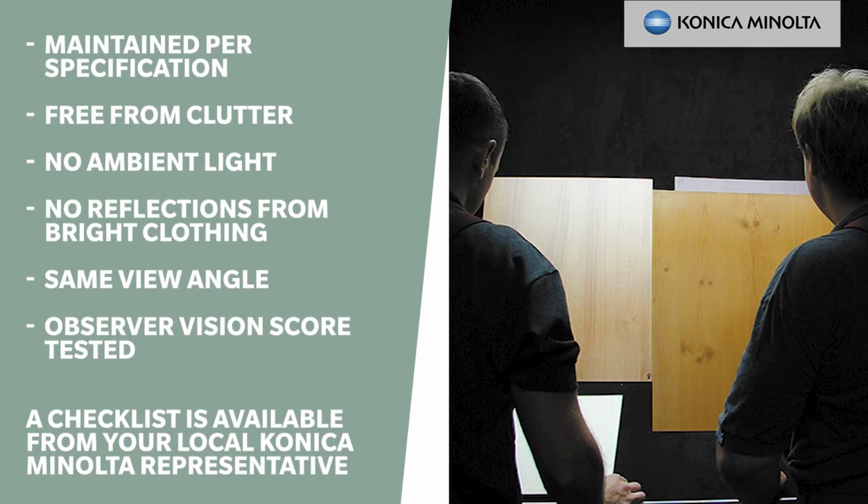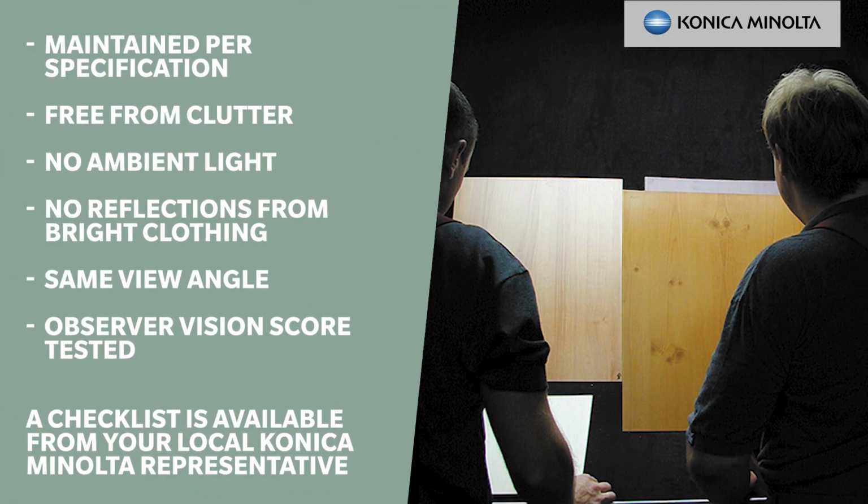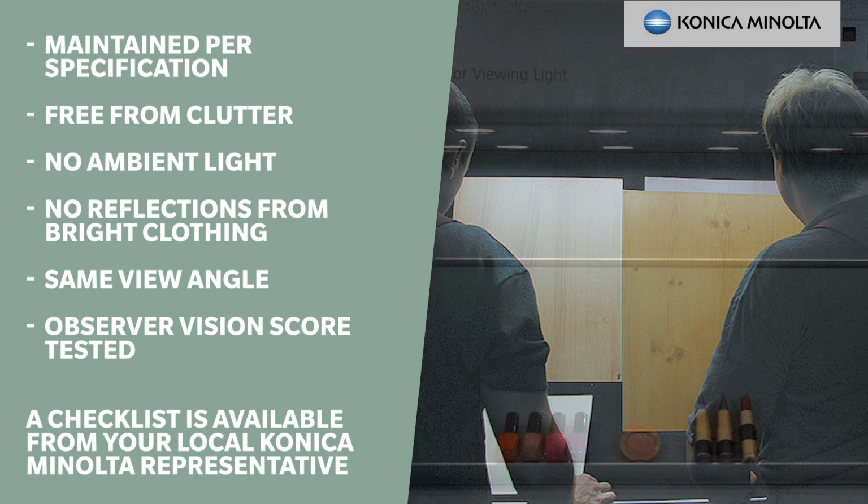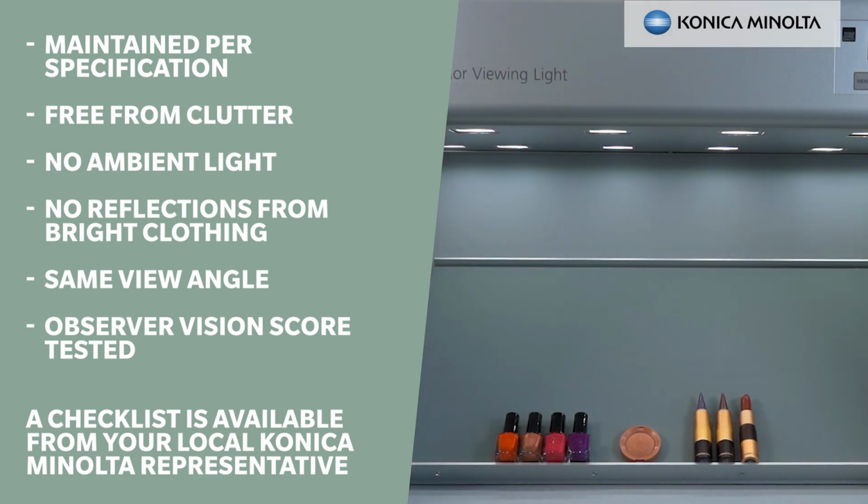When you use visual assessment in your processes, ensure that best practice is adhered to. Visual assessments and approvals should be performed in a colour viewing cabinet. That cabinet should be maintained per manufacturer's specification, free from clutter, and there should be no ambient light entering the cabinet. That includes the reflections from highly reflective or brightly coloured clothing. Observers should view the sample from the same angle.